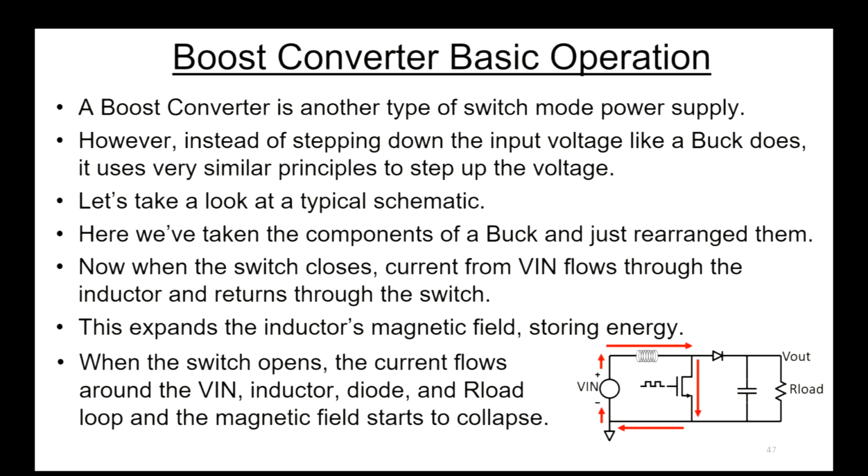So a boost converter is another type of switch mode power supply. However, instead of stepping down the input voltage like a buck does, it uses very similar principles to step up the voltage. Let's take a look at a typical schematic. What we've done here is we've taken all the same components of a buck and just rearranged them. Now, when the switch closes, as shown down below here, current from Vin flows through the inductor and returns right through the switch. It flows in this path right here.